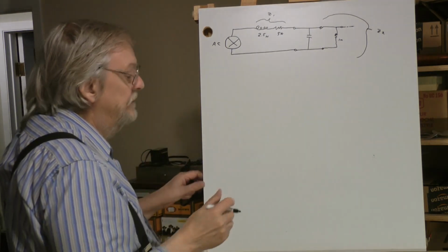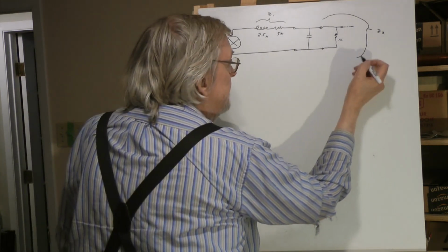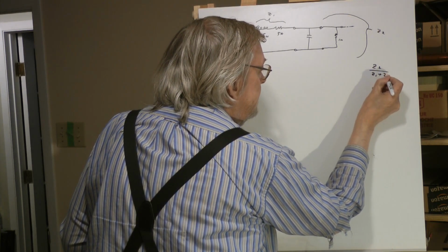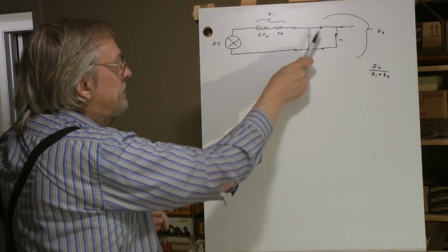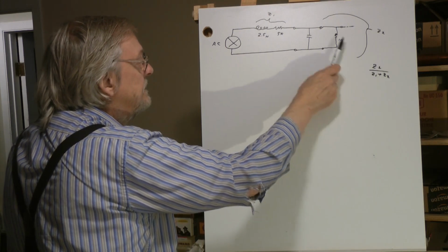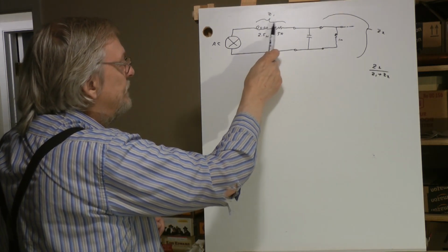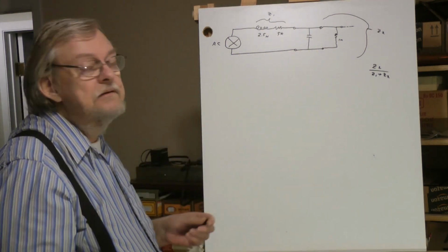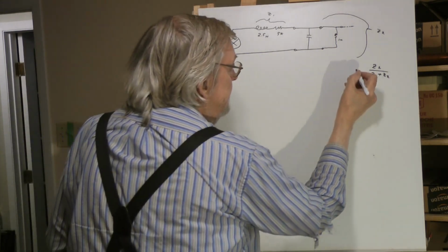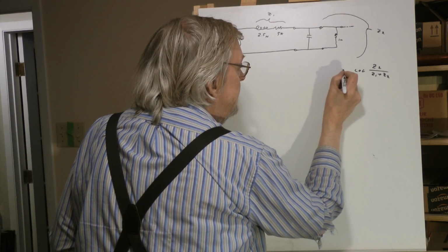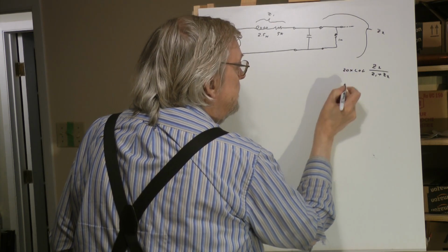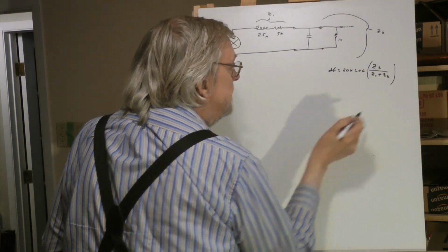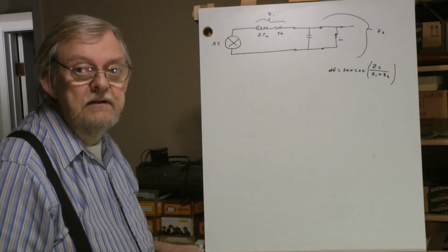Okay, so talking about the division, the formula to calculate it would be Z2 over Z1 plus Z2, right? So whatever is here, you'd have Z2, say that was 1 and that was 1, you'd have 1 over 2, which is a half. Equal resistances, it would be a half, right? So that's the formula. To get it into dB, we would need 20 times log, so dB loss equals 20 times log of this. That's just to get it into dBs because we're dealing with audio.